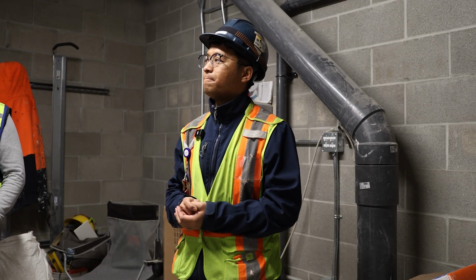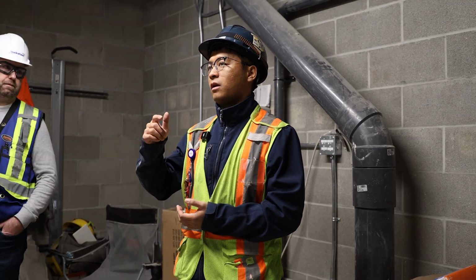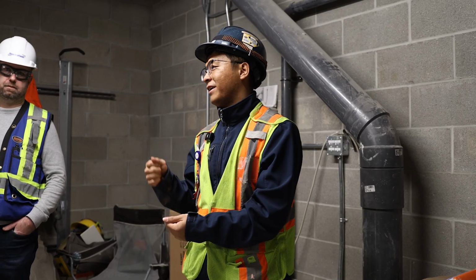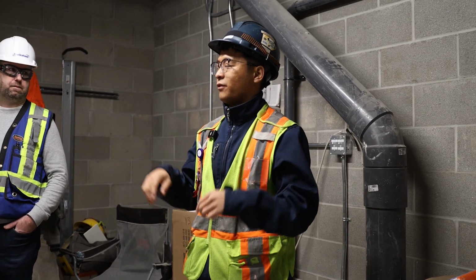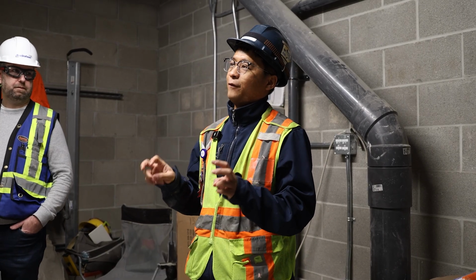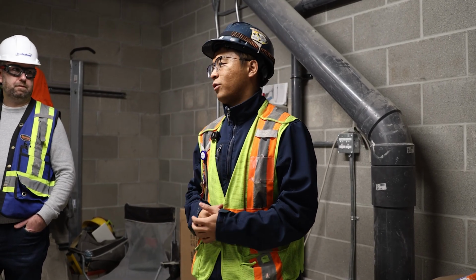But that filter alarm, it measures the filter differential pressure only when the MUA is running, right? Yeah. If that is not running, the differential pressure will just be 0. You may not see it. So you will see the filter alarm when the MUA is running.